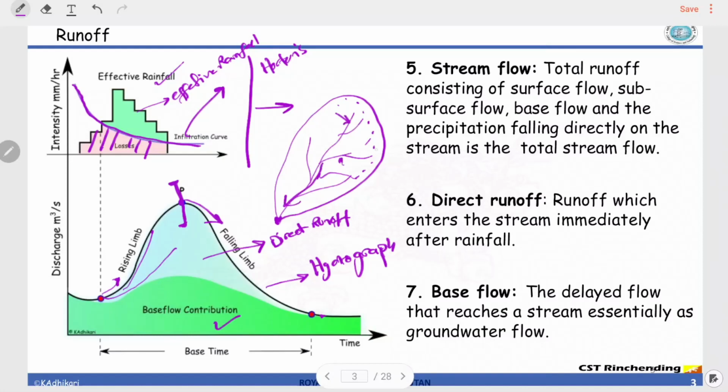But some portion of water infiltrates into the ground, and this also starts to flow, as I explained, laterally. Some rainfall may come out at the catchment surface again, but most of it flows as groundwater flow, and it will again contribute directly at the mouth, but you cannot see this. That portion is what we call base flow. Usually in our analysis we have to find ways to remove this base flow if we are only analyzing the direct runoff. We will discuss how to remove this base flow from a hydrograph in subsequent chapters.